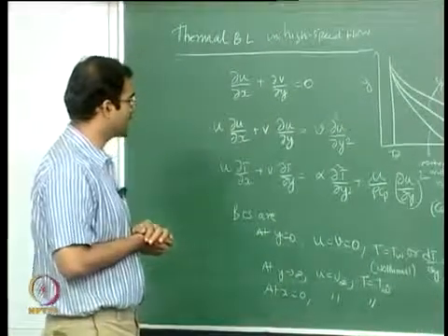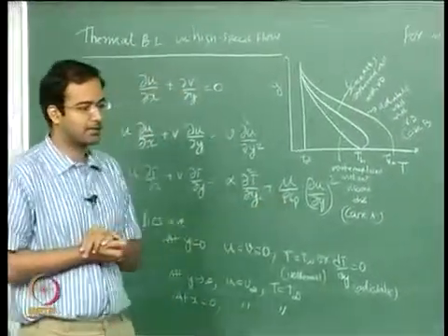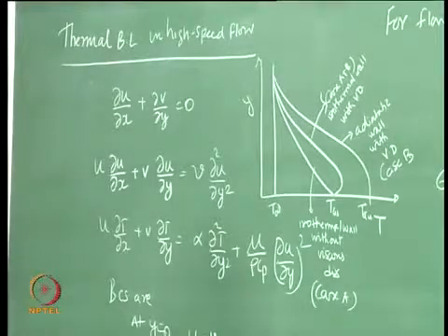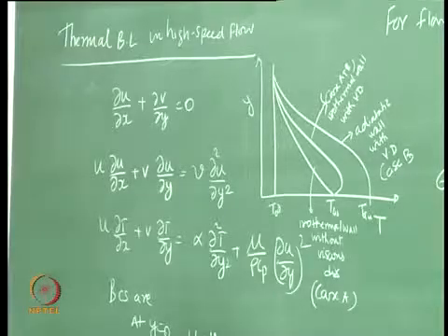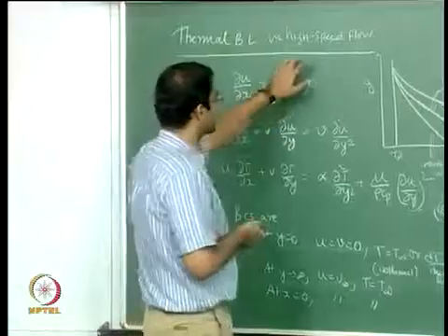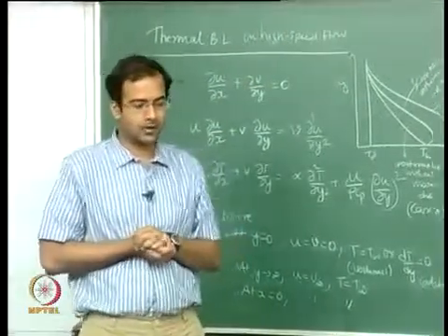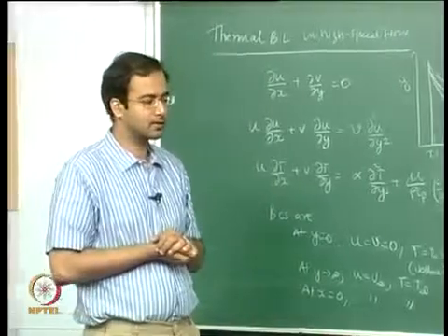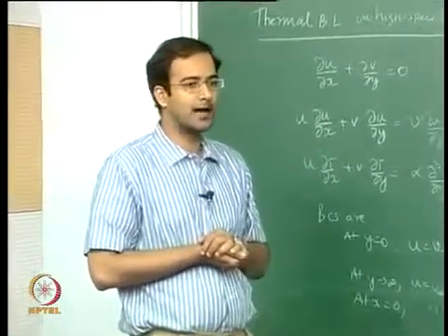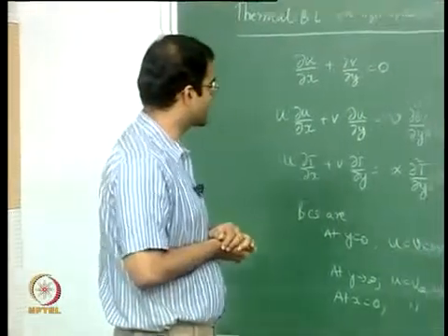Primarily, if you look at the non-dimensional variables, it turns out to be the ratio of Eckert number by Reynolds number. So for high values of this, the viscous dissipation term is going to be relatively important. So we are looking at typically what are called high speed flows. It could be incompressible and somewhat compressible but not supersonic. So it is relatively high speed subsonic flows. Basically that's what we are interested in.